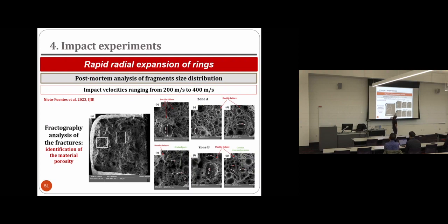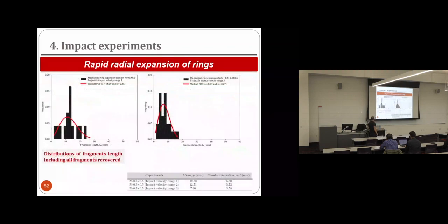And you can see here, for instance, these large voids. Okay, so this is almost 90 micrometers in diameter. What is interesting is that between the voids, we have dimples. So this is kind of ductile fracture, despite we have these large voids. So certainly the voids are really playing a large role, but in the, let's say, matrix material between the voids, we have something like a relatively ductile fracture.